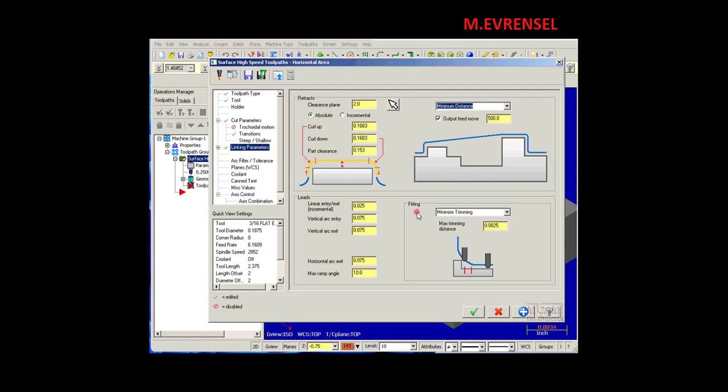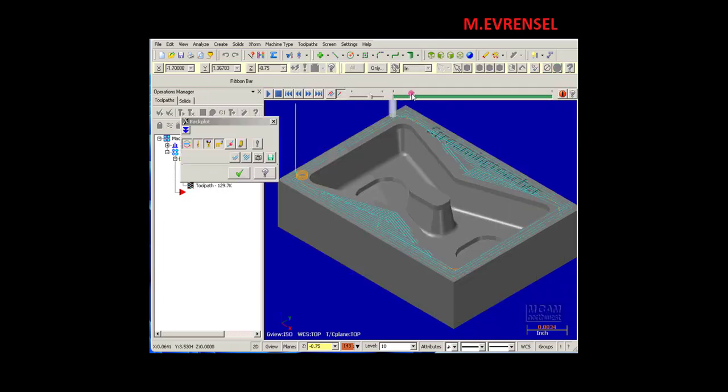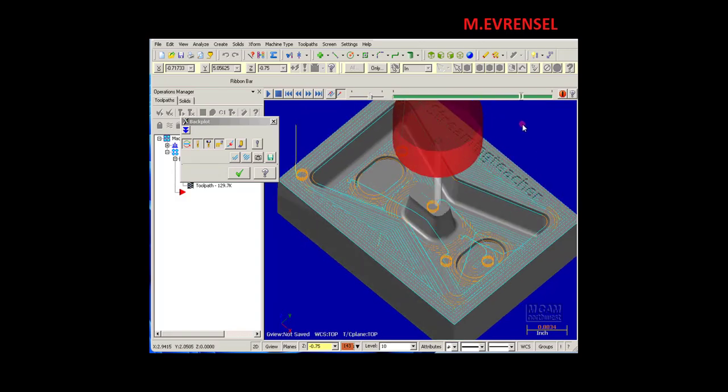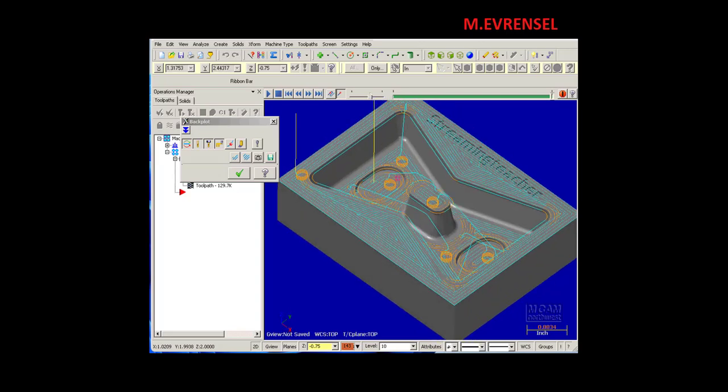And we'll go ahead and leave all the other defaults and take a look at what we've got thus far. Now right off you'll notice the first problem we have, the tool is machining the top of the part. We certainly don't want that because that's going to be faced with a regular facing tool. Then the tool goes in, finishes all the flats, top of that boss, and each floor. You'll notice that it's using a nice helix motion to get into each pass. So let's go in and make one quick adjustment to keep the tool off the top and just inside our part.